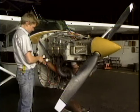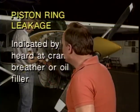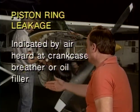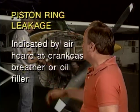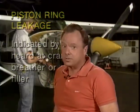If it's past top dead center, it's going to rotate the whole engine around when you put pressure on it. Now let's assume you're doing a differential compression check just like this, and you hear air coming from the crankcase breather or the oil filler. What's that a sign of? Well, let's take a look at it. If you hear air coming from the crankcase breather or the oil filler, it's a sign of piston ring leakage. Just an example of a piston ring leakage situation, tough situation there.